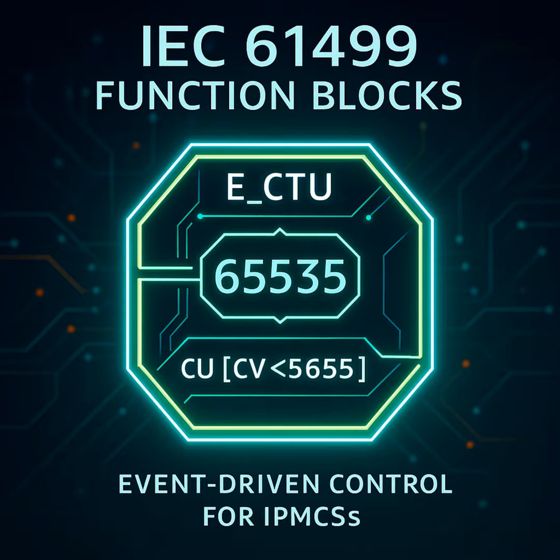I like that. For tracking something, say fast sensor pulses from a chopper drum or something, you want it to count exactly when the pulse arrives, not whenever the scan cycle gets around to it. Absolutely. So what events does it actually listen for? There are two main event inputs. Okay. First, you've got CU. That's your count-up event input. That's the pulse that makes an increment.